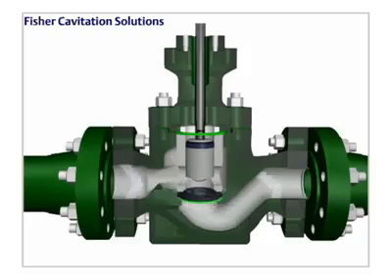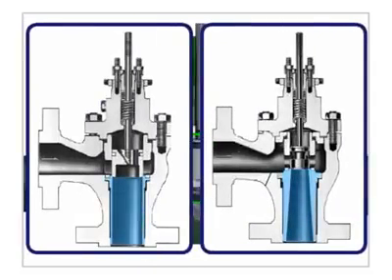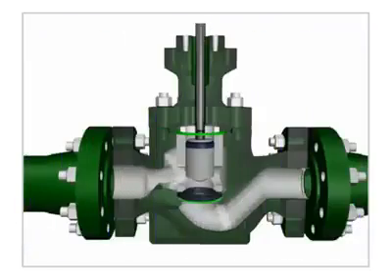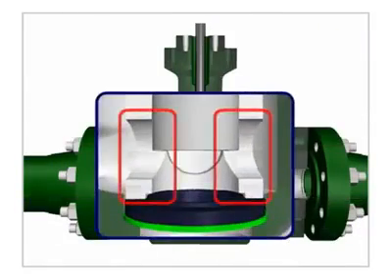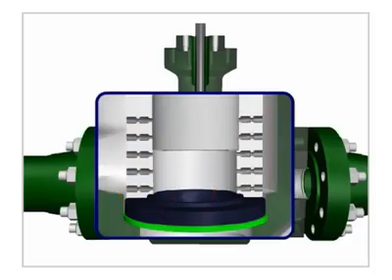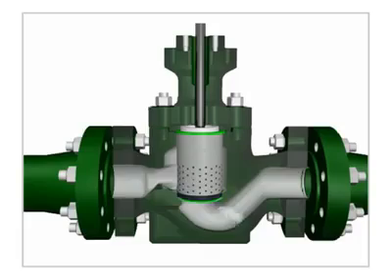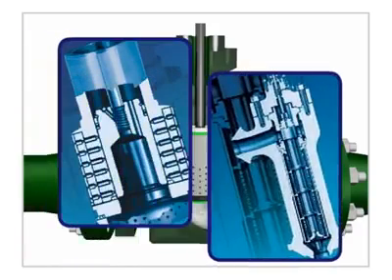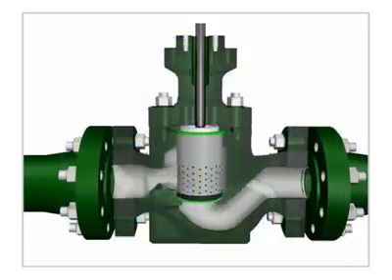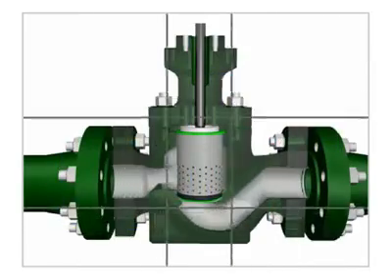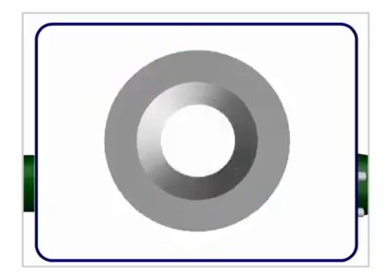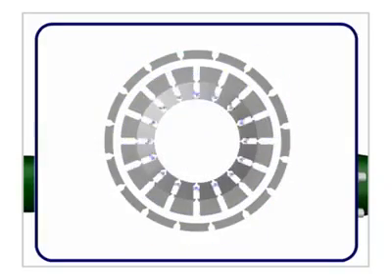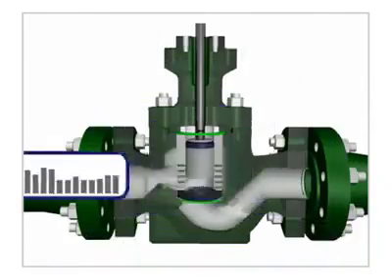Emerson offers these solutions. Valve liners are constructed of hardened materials to protect the valve body. Pressure staging keeps the pressure from falling to near a liquid's vapor pressure, which helps prevent vapor bubbles from forming. Pressure drops are staged by the use of expanding nozzles or expanding flow areas. For example, in the Cavitrol 3 valve trim, nozzles have holes shaped to manage flow separation. Multiple small holes shift the noise to higher frequencies.